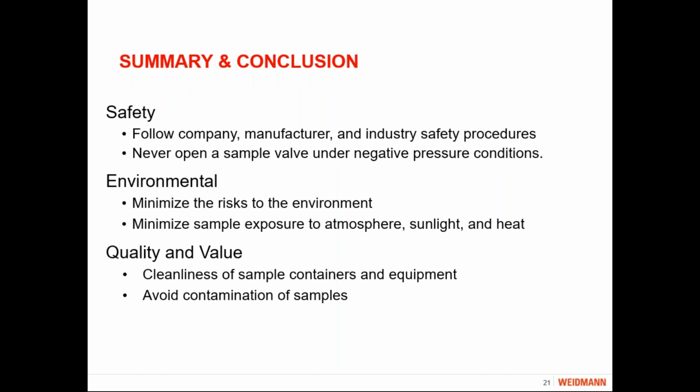So in conclusion, whenever you take a sample, you want to make sure that you're doing it safely. Make sure that you can safely access the sample port. Now, if it's a pad mount transformer and that sample port's inside the compartment where the cables are, follow your own local, state, and company safety regulations. Some companies will not allow you to open the cabinet if the transformer is energized. So if the company you work for has that rule, make sure you de-energize the transformer before you take the sample.